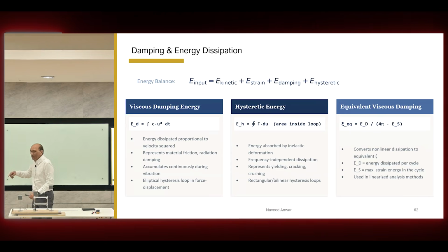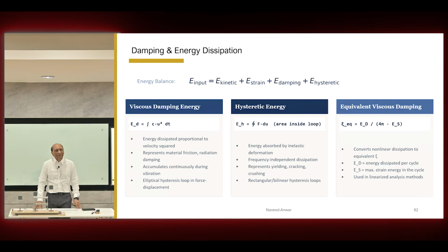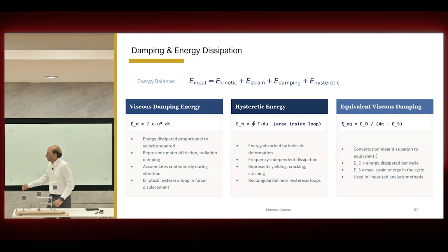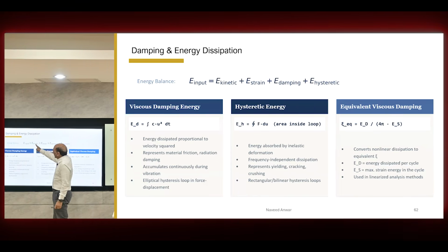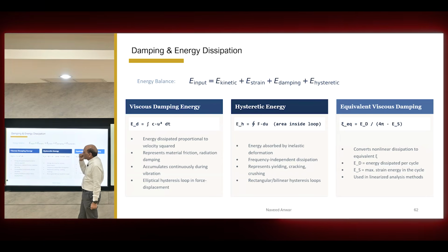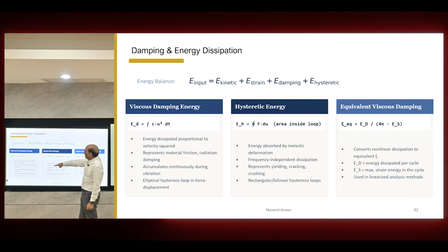That's why in nonlinear analysis, in performance-based design, we always look at the energy dissipation plot, the share of energy dissipation. So we have the kinetic energy, and then strain, and the damping. Damping further has 3 parts: viscous damping, hysteretic damping, and equivalent viscous damping.